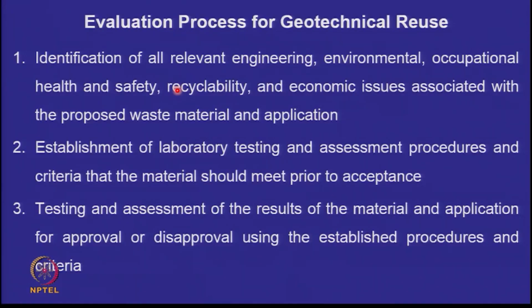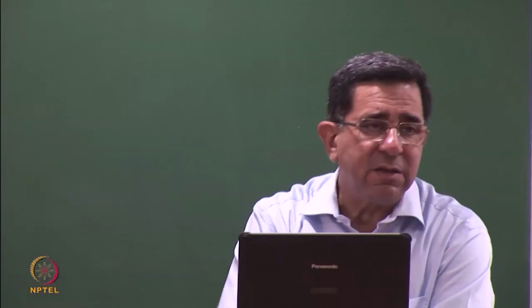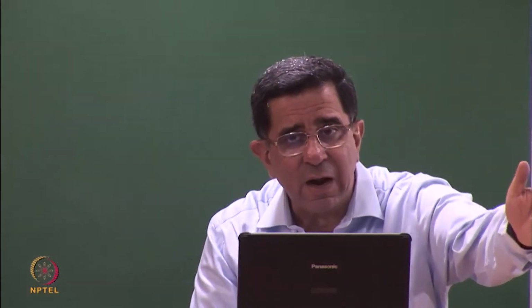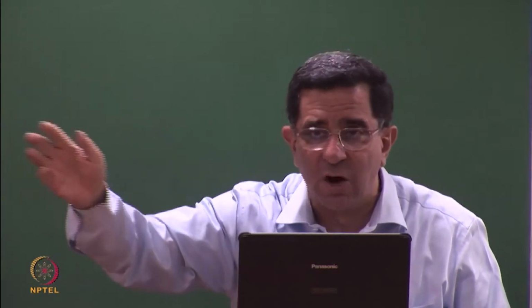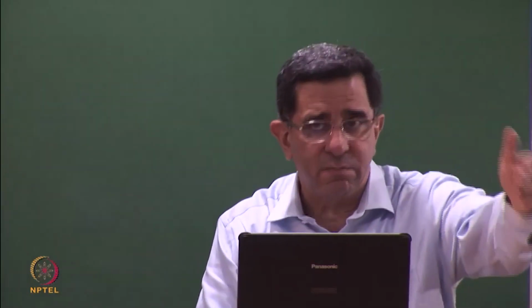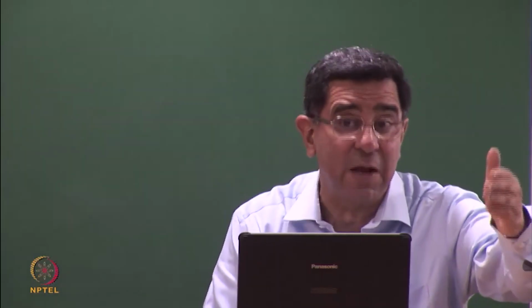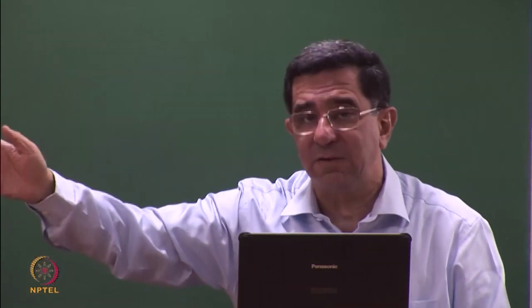So finally, I'd like to say that if you are doing geotechnical reuse, we are going to look at all the relevant engineering for each waste. Please remember that just because person A used slag at one location, person B getting slag from another plant may not be able to use it. Similarly, if person X used coal ash from a particular thermal power station which may have no sulfates, person Y cannot use it from another thermal power station which may have sulfates.